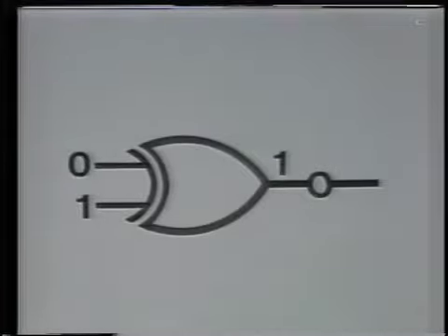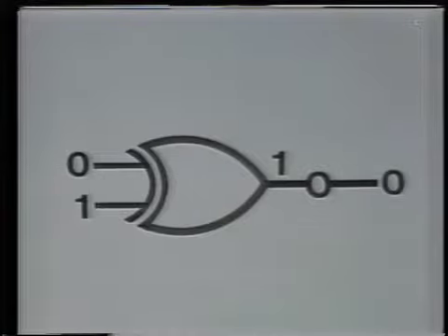Determine what the output would be by using our previous technique for exclusive OR gates. Run that output through the inverter, and the output shown on the inverter should tell us what the output of the exclusive NOR gate is. The exclusive NOR gate is sometimes referred to as a coincidence gate. The reason for this is because the inputs must be the same, or coincidence, to have a 1 output.